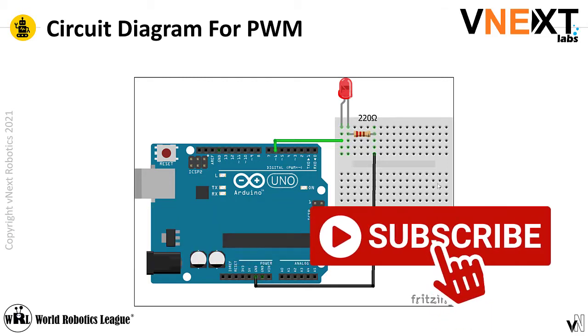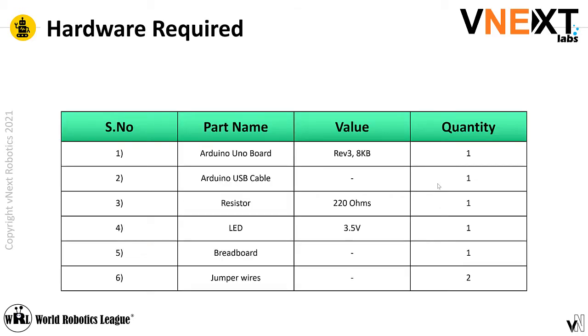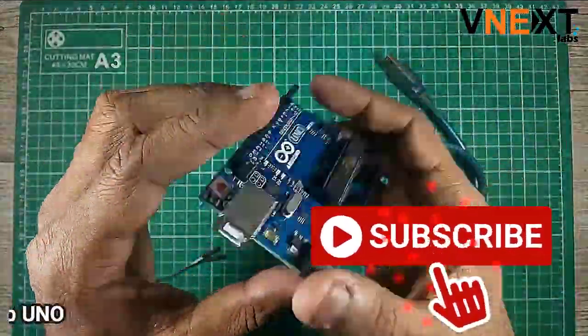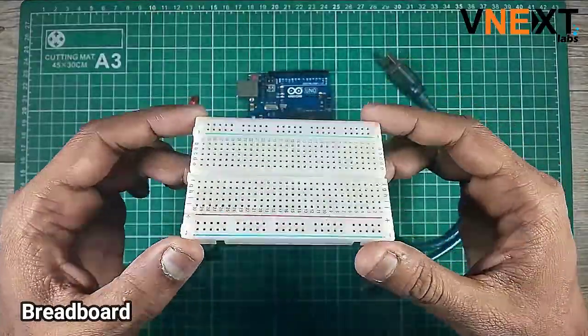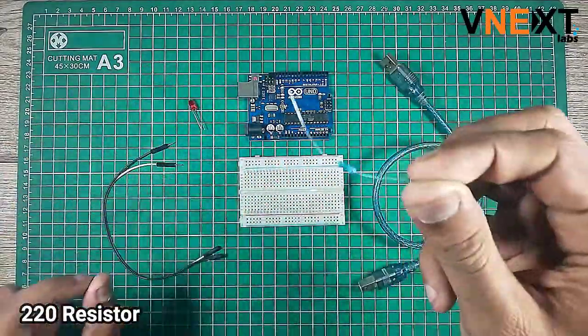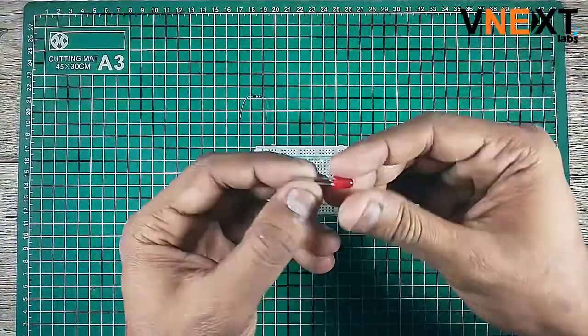Here is a simple circuit for generating a pulse width modulation at the digital pin number 6. Here is the list of components that are required to build this circuit. One USB cable to connect the computer to the microcontroller. One breadboard. One LED. One 220 ohm resistor. Some jumper wires. Let us connect the resistor on the breadboard.